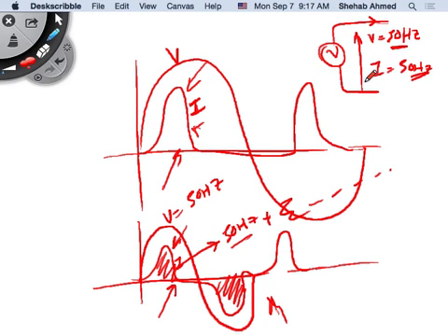So what is the real power delivered by the source? It's only the 50 hertz voltage multiplied by the 50 hertz current, then cosine of the power factor angle. That's the real power transfer. But there are lots of other components. These other components are called harmonics, and they cause a distortion in the sinusoidal signal. They distort the sinusoidal signal, but they exist.